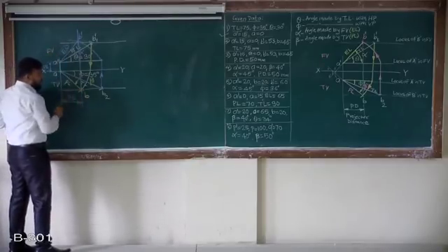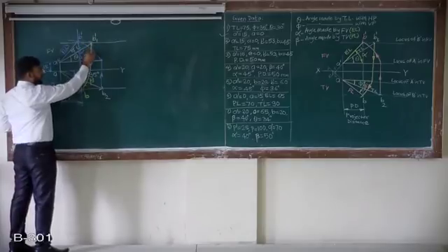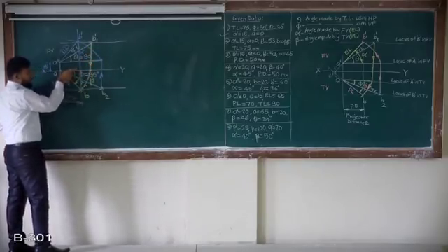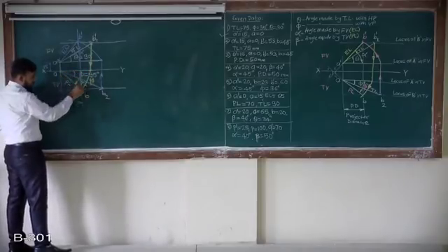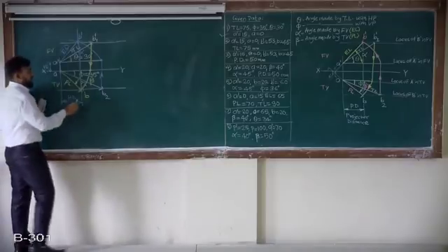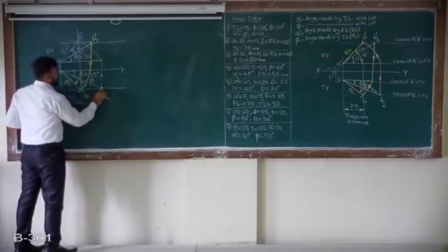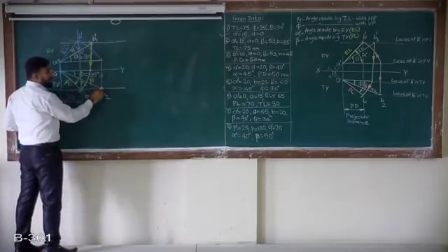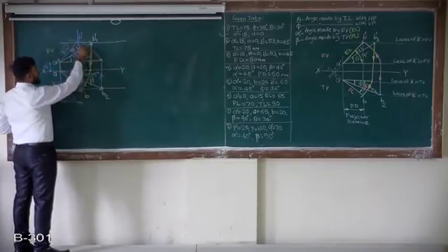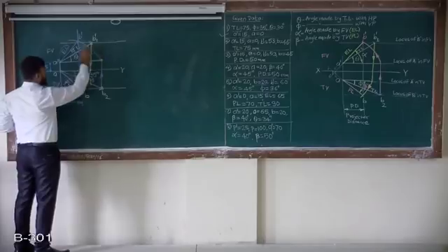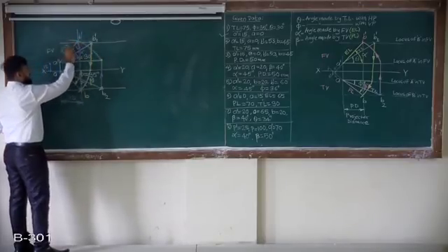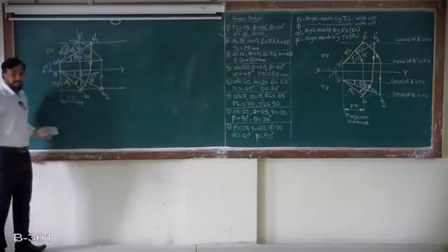To get point B, I projected B1 dash onto the locus of A, then with A as a center, rotate this, and you will get the point B. In a similar way, project this point B2 onto the locus of A dash and again rotate onto the locus of B. You will get this point as B dash and this corresponding length as EL.